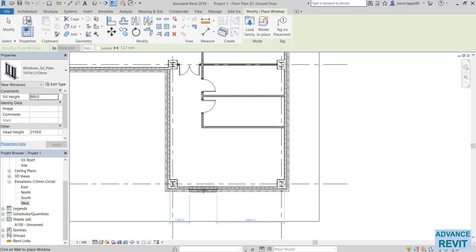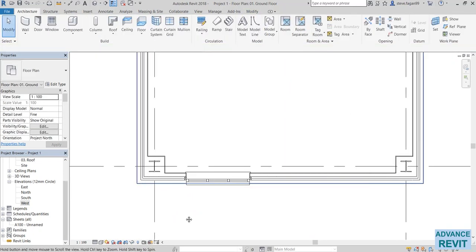So a little trick to know where the exterior face and the windowsill of that window is. You can tell that by the temporary dimensions. So if I hover over the wall, having the cursor down the lower half, you can see my temporary dimensions are outside. So I know now that when I place this window, the external face of the window is placed to the external side. If I move my cursor above the wall, the temporary dimensions go inside and my window is incorrect. So just click once to place and zoom in.